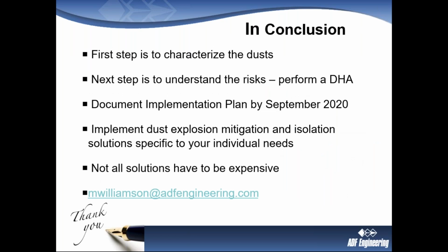So in conclusion, the first step is you need to characterize your dust. You need to understand what you have. You need to understand the risks, perform that DHA. And you need to have your implementation plan in place by September of 2020. And you need to follow that implementation plan. Keep in mind that these implementation plans do not necessarily have to be expensive. There are a lot of different ways to do this. So with that, if there are any questions,